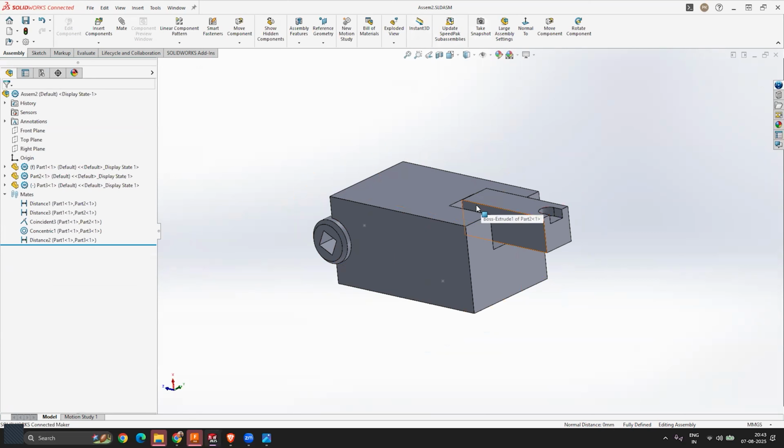And whenever you will be sharing your assembly file with anyone, you cannot simply save it and share it, because this assembly file is connected with 3 components also, right? And those components are part 1, part 2, part 3. So whenever you are sharing any assembly file with anyone, don't just save this file and share it. That will go with only the empty information where these 3 parts will be missing, and your assembly file will give an error. So how can you share your file?